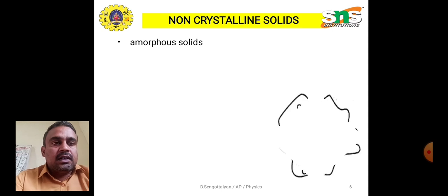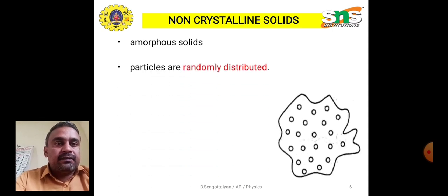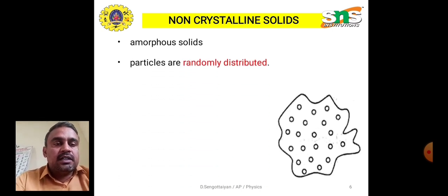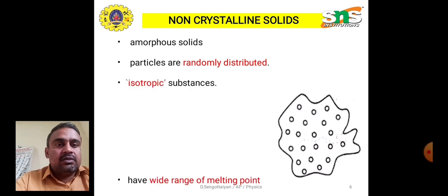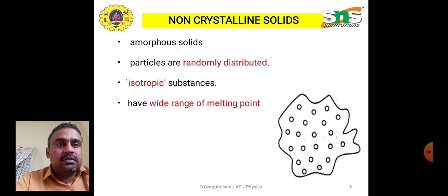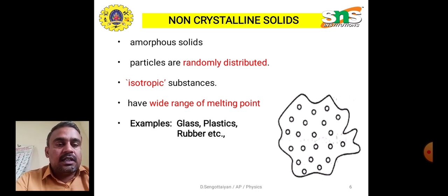The next one is non-crystalline or amorphous materials. The particles are randomly arranged. They are isotropic substances. So non-crystalline materials have a wide range of melting points. Examples for non-crystalline materials are glass, plastics, and rubber.